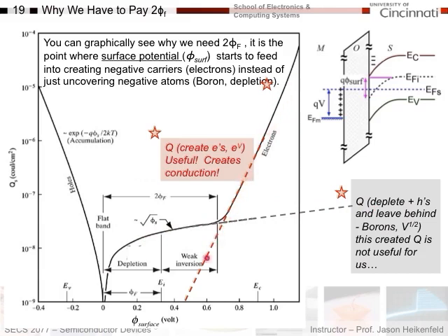But look, here's if I project the growth rate for electrons through here, basically what happens is that my voltage is always feeding in, and it's always creating some electrons too, but the electrons don't start to take over until they surpass the mathematical growth rate for depletion charge. So I'm depleting with the square root function. Then all of a sudden what happens is that electrons start to appear, but they are able to generate charge exponentially. So the key point is that this function dominates over charge for depletion. And so what happens effectively is this function just goes away.